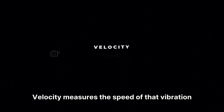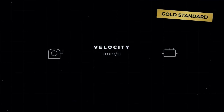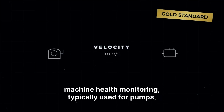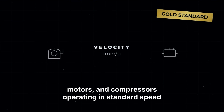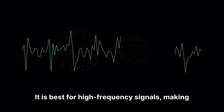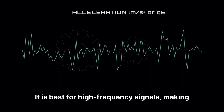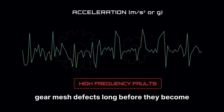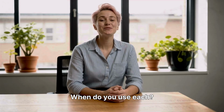Velocity measures the speed of that vibration in mm/s. It is the gold standard for general machine health monitoring, typically used for pumps, motors, and compressors operating in standard speed ranges. Acceleration measures the rate of change of velocity. It is best for high-frequency signals, making it essential for detecting bearing wear and gear mesh defects long before they become visible. When do you use each?